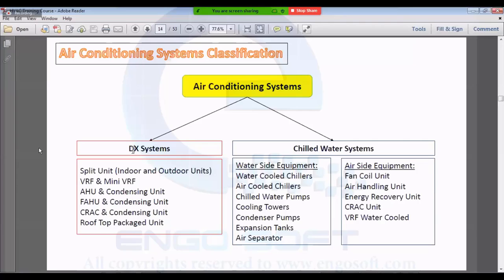By inserting fresh air, which is at 46 degrees, into the space, we have to pay a lot to cool this fresh air, because we have to cool it from 46 to 24. So it is very expensive. So we insert a small percentage that is enough to remove the pollutants, odors and smells from the space, while the remaining air is provided from the same room air, which is the return air.